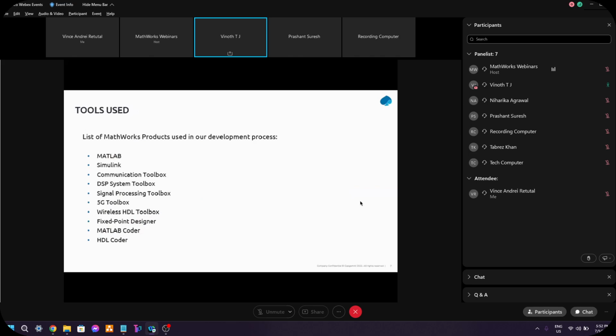So pros and cons have been considered using all these toolboxes, like specifying the IQ bit width. Majorly, in specifying the IQ bit width, we faced some challenges at each and every stage of this design. That has been successfully simulated using these toolboxes, and our design verifies our bit-level accuracy against all the IQ samples for all the downlink and uplink channels against these toolboxes.